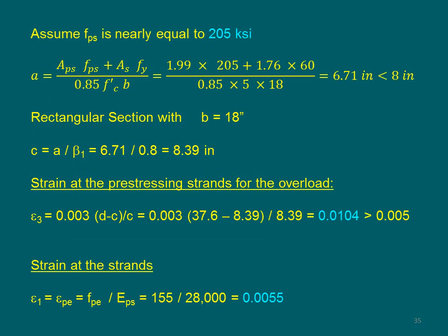This third component for the strain of the steel is going to come from the capacity point. At the capacity point, we should be able to determine the compression block depth a if we have the total tension in the steel, the concrete strength, and the width of the concrete beam. To start with the nominal stress in the pre-stress strands, I need to start from some point.